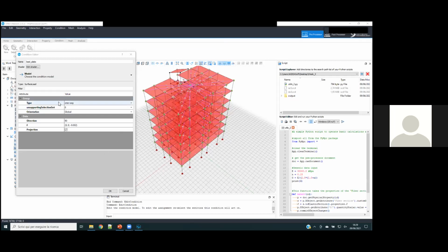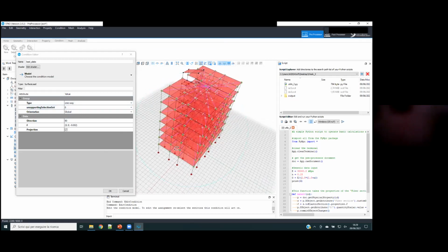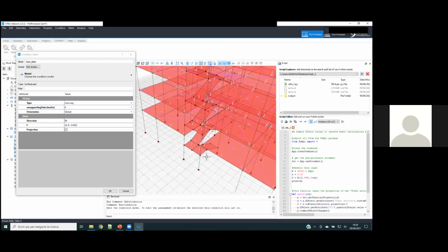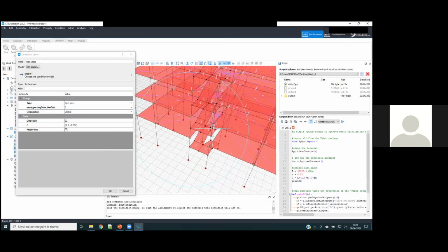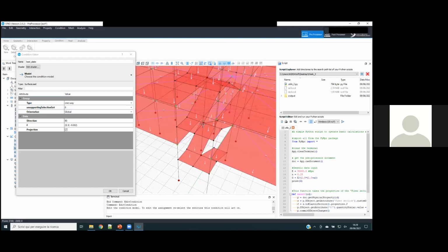What is it that is specific about this command? If you have, for example, here, I had to divide this geometry because I wanted my mesh to have everything as one single element. So if I hadn't put this here, my face would have been made of 5 nodes, and I couldn't have a quadrilateral element when I meshed.